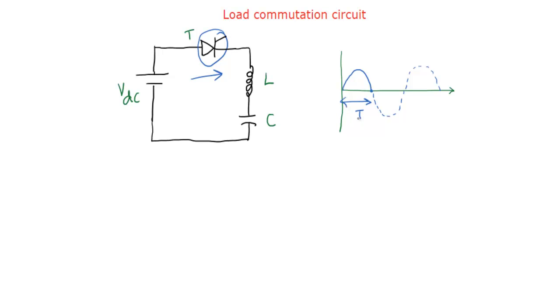That duration is nothing but T. Okay, you can use the small t. That T is nothing but omega naught t, because the frequency here is the resonance frequency, that's why omega naught t. That is equal to how many radians? We know that it is pi radians. So in case of an undamped system, the thyristor will be in conduction for T seconds.